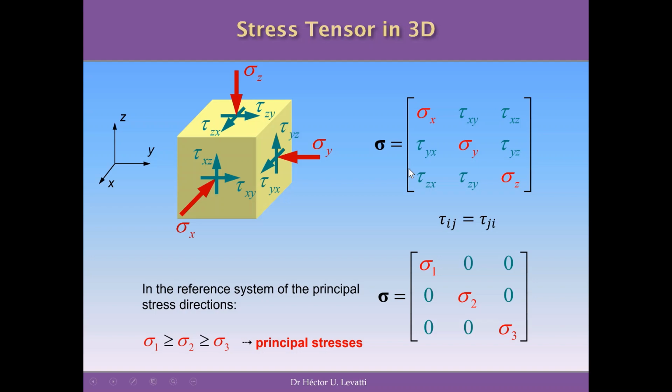You know as well that there are stresses that we call the principal stresses. Principal stresses are stresses in certain directions at a point in the soil mass or in a structure where the shear stresses are equal to 0. A stress tensor can be as well the stress tensor of the principal stresses, where the shear stresses are equal to 0, and you have as principal stresses sigma 1, sigma 2, and sigma 3.